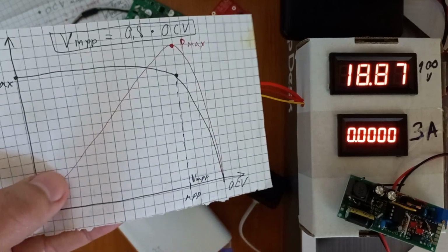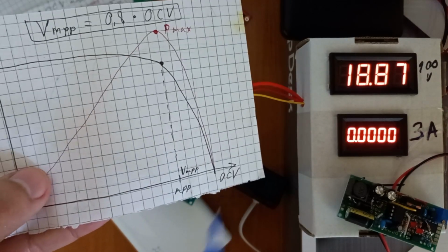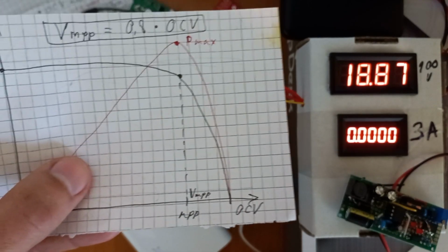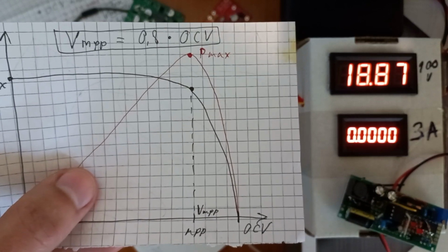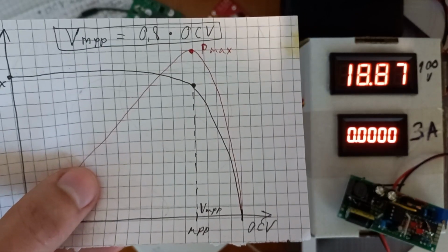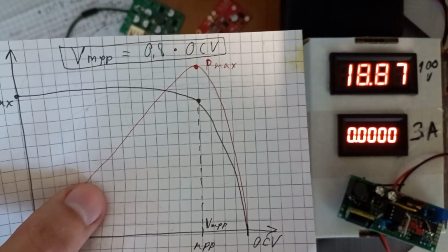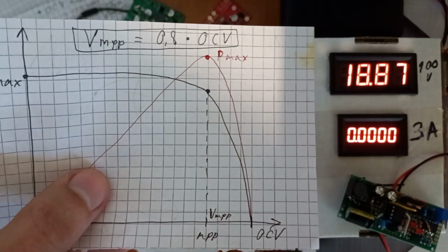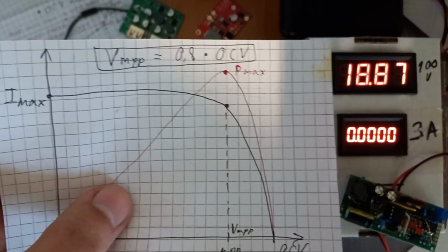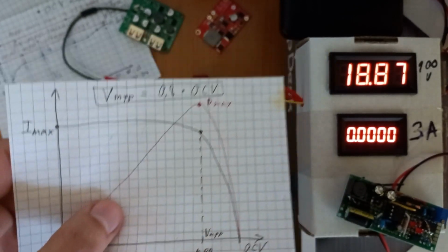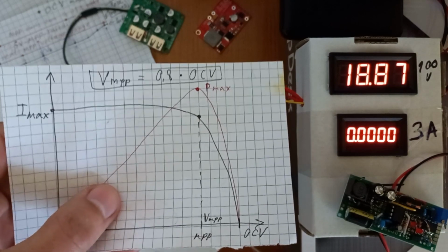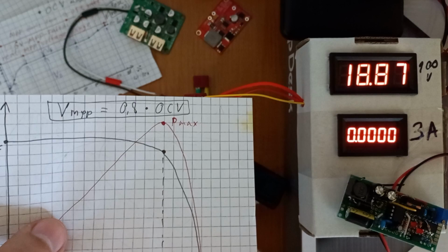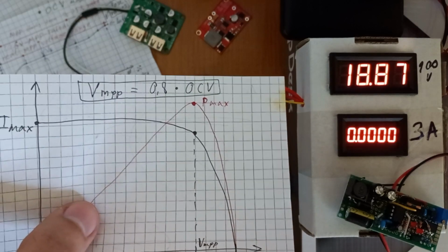Here are OCV, open circuit voltage, and MPP, maximum power point. MPP is always around 80 to 81% of OCV. It doesn't depend on amount of solar energy nor on panel temperature, while actually solar panel efficiency rate depends on its temperature. Lower temp is better. MPP rating always refers best conditions and likely won't be achieved by real users, so expect to receive some like 10% less in a good case.